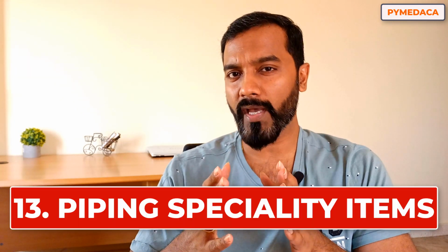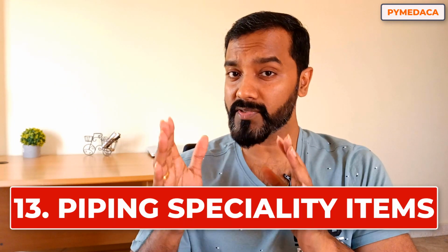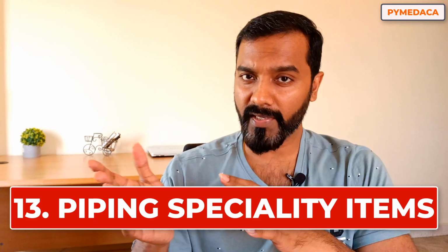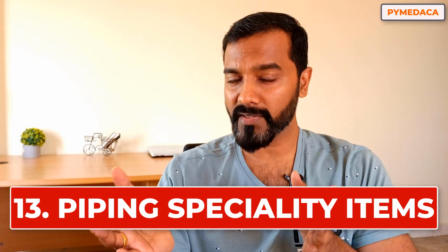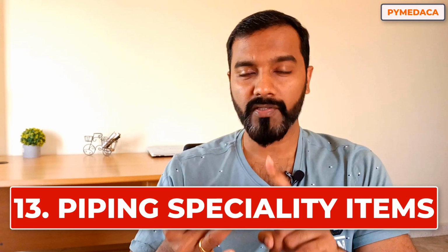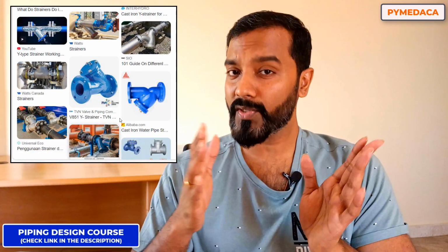The next input you should have is piping specialty items details. So what are piping specialty items? There are many piping specialty items, for example, filters, strainers, rupture discs, orifices, and flanged spools actually. All these things are considered piping specialty items. You need to have the rating, the size, and the dimensions of these so that you can include them in your piping design. Unless you receive this information, you cannot finalize it.